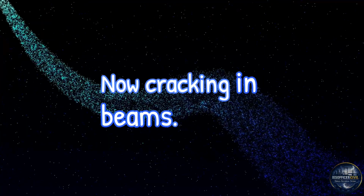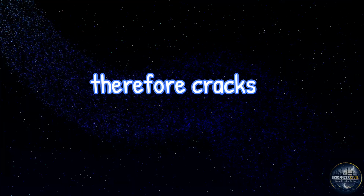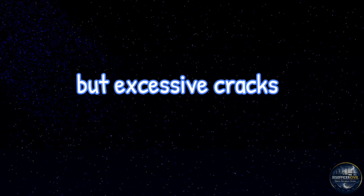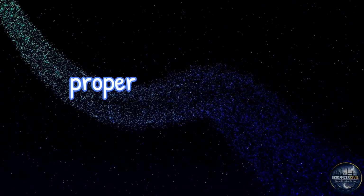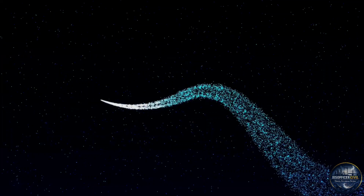Now cracking in beams. Concrete is weak in tension, therefore cracks develop in tension zone. Fine cracks are acceptable within permissible limits, but excessive cracks reduce durability and allow corrosion. Proper reinforcement spacing, proper cover, and proper detailing help in crack control.